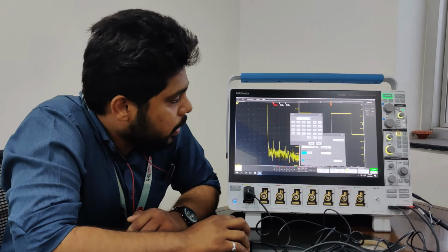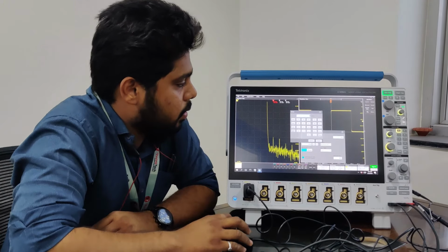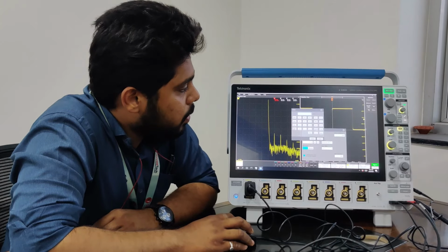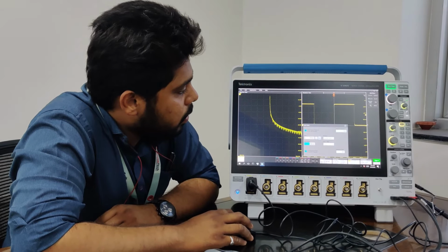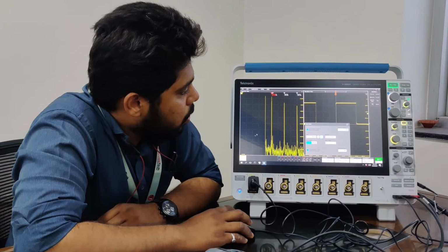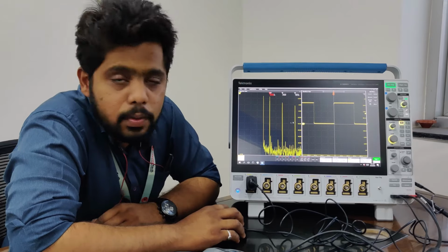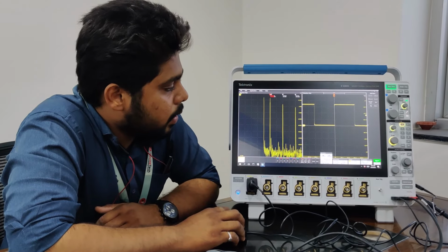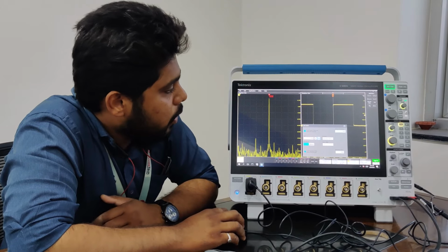And this is the span of the signal. We can set it in megahertz. Let's see what happens if we set it to 1 mega. Okay, so it is showing some noise. Here you can see this is my 1 kilohertz signal, and these are the sidebands which are present over here. I can just increase or decrease it, like 10 kilohertz, 5 kilohertz, and so on.